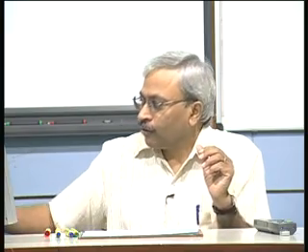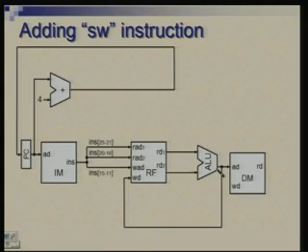We will use this ALU itself to calculate the address. For doing PC+4, we could not use this because we had instructions which were using it for some other purpose, and this PC+4 was being done over and above all that. So, we required a different piece of hardware here, but for load store instruction, we will use ALU to do the address calculation, and therefore, I have connected it in this manner.